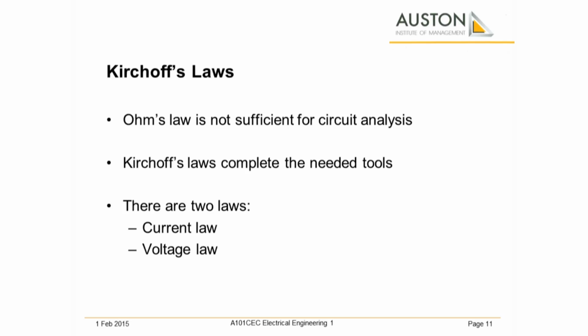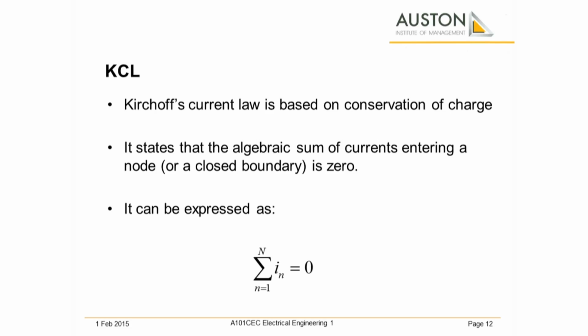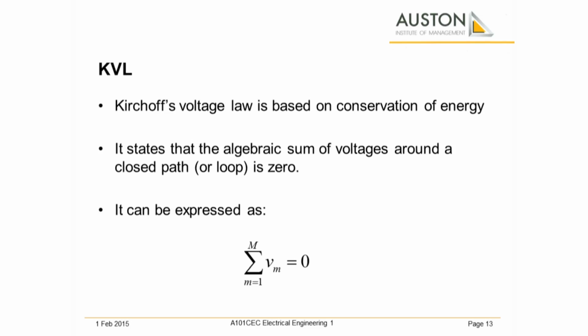KCL, or Kirchhoff's current law, is based on conservation of charges. It states that the algebraic sum of currents entering a node or a closed boundary is zero. In other words, we can say that the summation of current entering a node is equal to the current leaving that node. KVL, or Kirchhoff's voltage law, is based on conservation of energy.